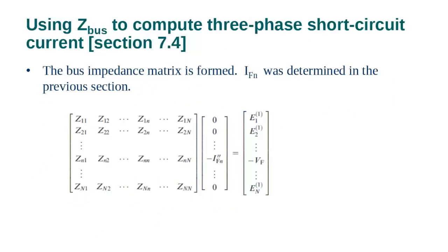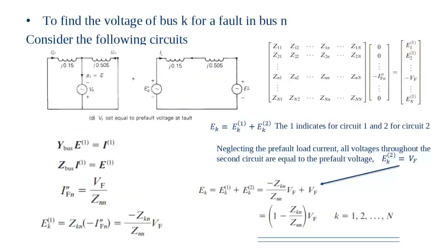And the last time we reached this slide here, where we discussed the voltage and how to determine the current. This is what we're interested in. The current becomes high at the fault. That's why we are interested to find the current. Then we can set the circuit breakers. So when there is a fault current, you remember now the circuit breaker opens and then closes, automatically.